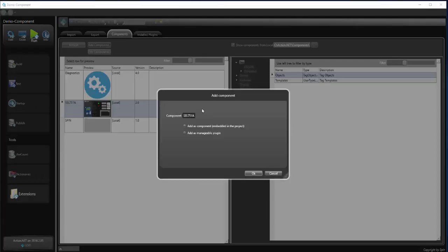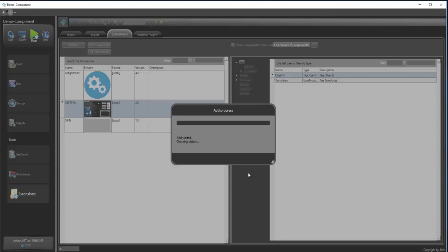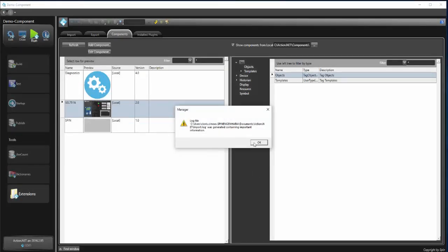This new component is considered to be developed by the manufacturer, or by an independent consultant, and has all the points of the relay suggested for use in a feeder bay, with its IEC 61850 addressing, all events and alarms associated with the relay, and all measures that go to historical. In addition, it already has an object that represents the feeder's schematic, and a detail screen of the feeder, built from the manufacturer's screen suggestion on the website. It is the relay best practice according to the manufacturer or consultant.